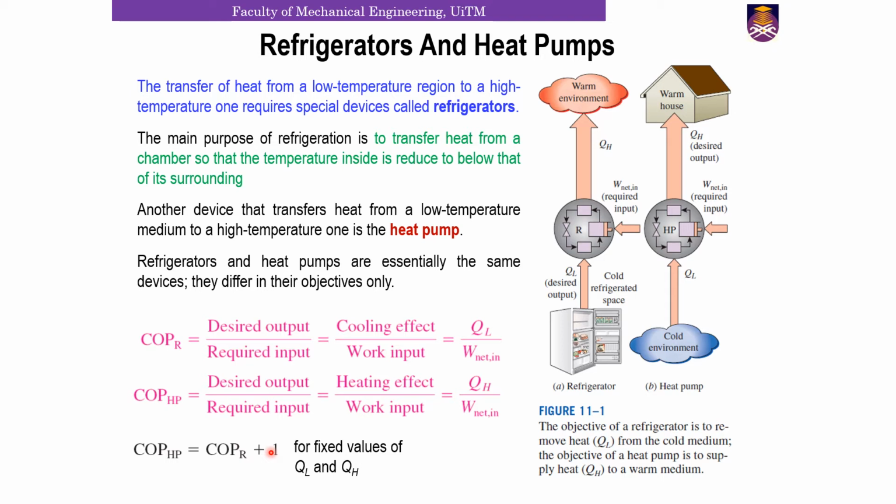That is, a heat pump functions at worst as a resistance heater, supplying as much energy to the house as it consumes. In reality, part of the QH is lost to the outside air through piping and other devices, and COP for heat pump may drop below unity when the outside air temperature is too low. So when this happens, the system normally switches to the fuel powered by natural gas, propane or oil, or resistance heating mode.